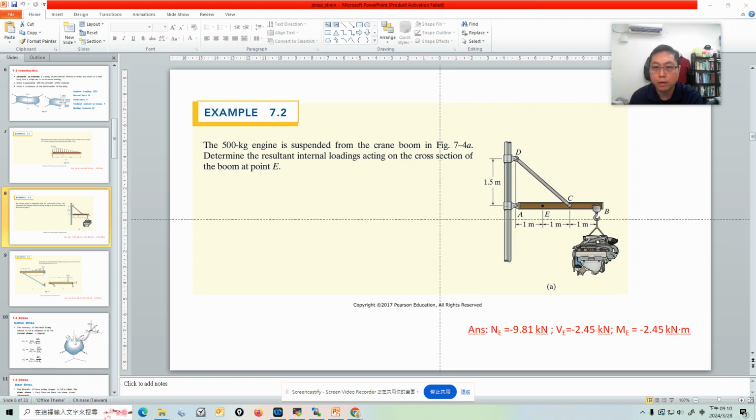For this type of question, first of all, we draw the free body diagram, and then we decide to cut the section using the cut section method. I choose to calculate from the right, not from the left. The problem didn't tell you, but there is a pin support. I choose the right because if you do this cut, you can ignore everything from the left, so you don't have to care about the support reaction from A.